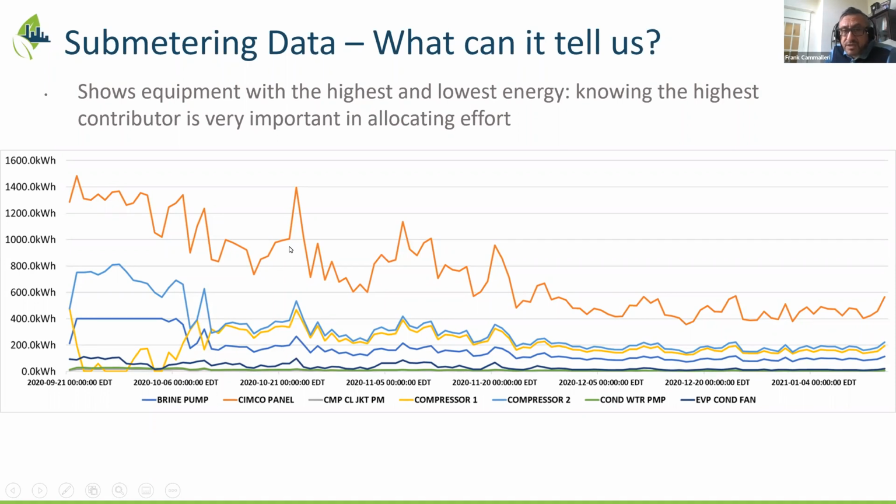Again, not just that you're sub-metering the refrigeration plant on its own, but what makes up that energy. Then we'll get into a little more detail about how you go even deeper than this to understand and make this process even more efficient. That's when you start using your building automation system to trend things that are not necessarily energy related. But one of the things that's really good about sub-metering this is that you capture the interactive effects of it.